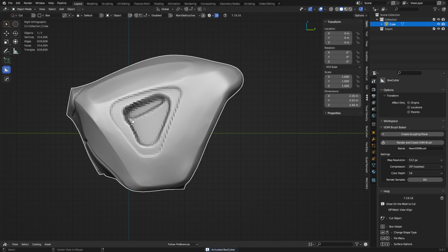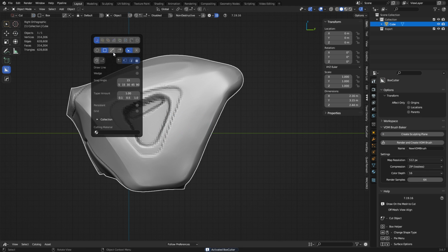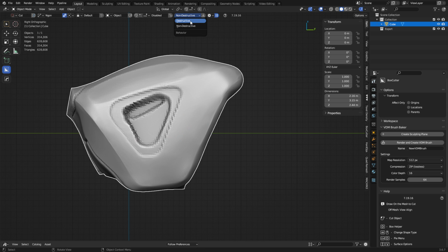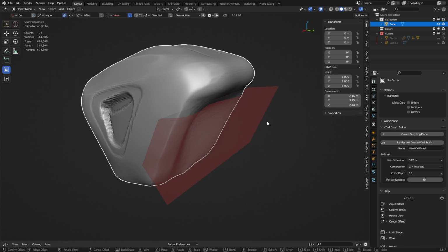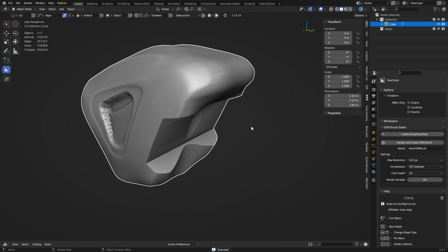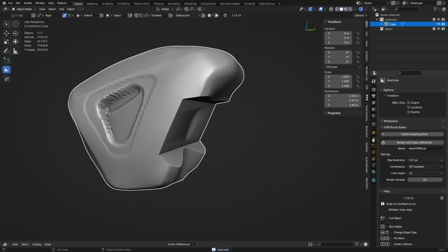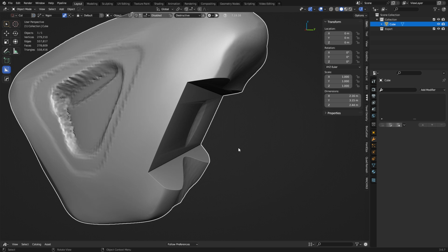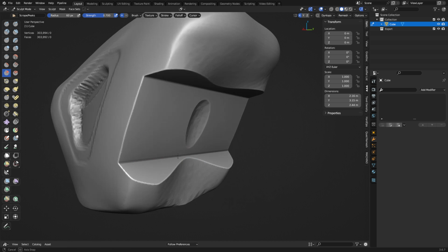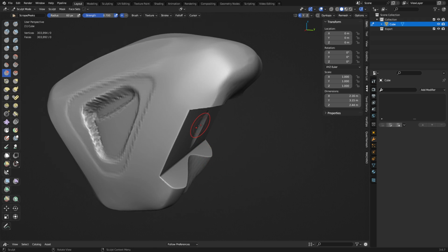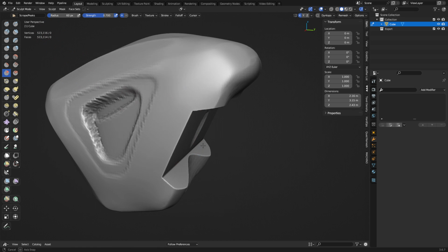So, for example, if I want to turn on Box Cutter and I want to use the ngon cutter, turn it to destructive and turn the live preview off. Okay. But now you can go through here and do booleans all day as long as it's low enough poly. You don't have the live update taking place, so as soon as you double click or whatever, it's going to do the boolean, and that's it, right? There's no boolean modifier anymore. And so we can go back into sculpt mode, hit Control R, remesh it, and you can see it's pretty clean right off the bat. So we can take the resolution up if we need to, as high as your system can handle, I guess, is perfectly acceptable.